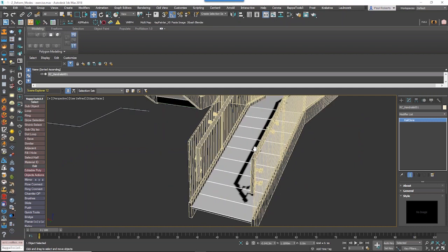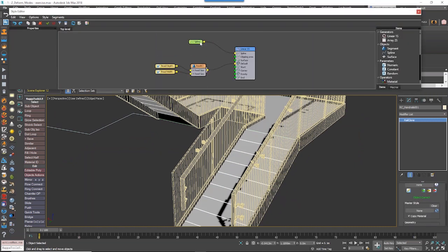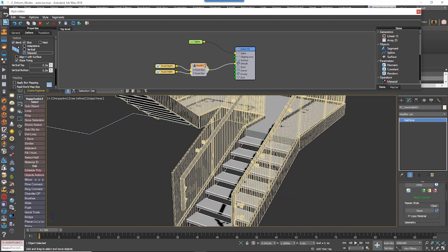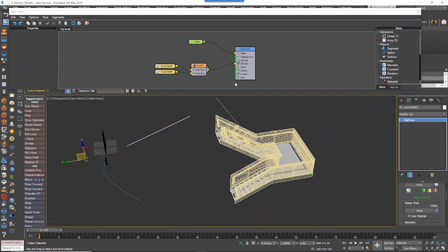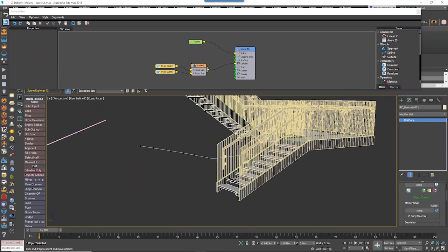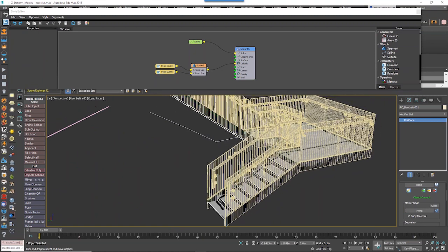So here I've got a staircase which is a little bit lethal looking. It's basically a slide. But I can easily just change the geometry that's in here to stepped mode, and I can create a staircase that's pretty easy to adjust and parametric. And if you wanted closed stairs, then you can get that same sort of effect by having different vertical tops and bottoms and that kind of thing to get a completely closed staircase. And there's a tutorial on our website if you want to have a look at that.